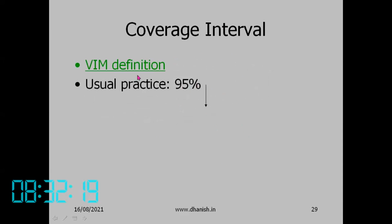So usually, practically in industry, we follow 95%. Some of the old books we had, in Dublin and elsewhere, used to follow 99%. But now it has been standardized, because 99% results in a very large coverage interval. The confidence interval becomes very large, so it becomes very difficult.